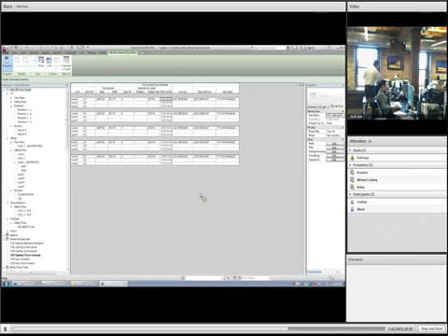Okay, here we go. You can delete level 2 dependents. Yeah, anytime you create a view off of that level, it will associate everything with that level. So when you delete the level itself, now, did I just delete fixtures? There should not be any fixtures. Were they hosted to that level?